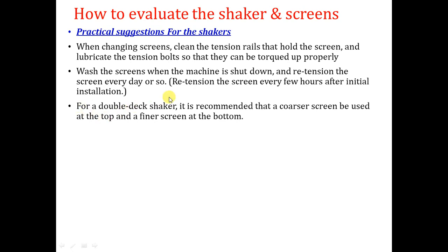This is very important. Why? Because the solids or the mud with its temperature can lead to some thermal expansion, which may make the apertures larger than required. So you have to retension, or check the tension of the screens, from time to time.